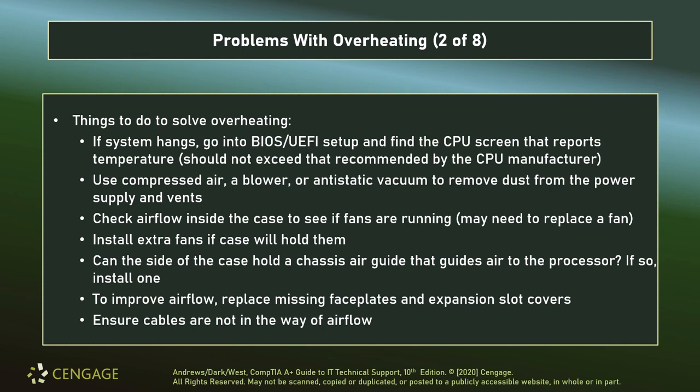Sometimes, of course, high-end graphic cards and power supplies can go a little hotter. It just depends, but CAGs are always helpful. I think Intel and AMD both recommend them. Make sure that your faceplates are clipped in place correctly, that you don't have things just sitting open. That makes it very difficult to get enough back pressure with your fans to force the airflow necessary to get a very high rate of air movement, cool everything down efficiently.